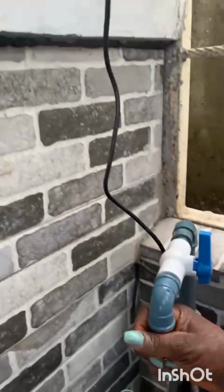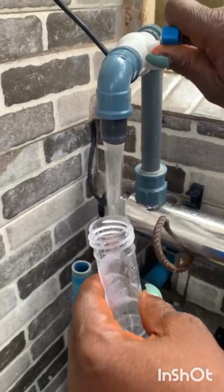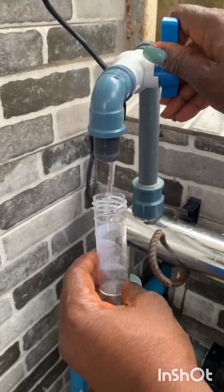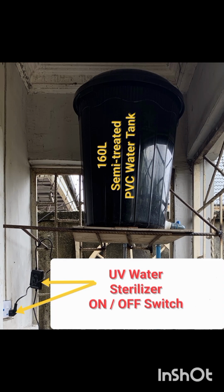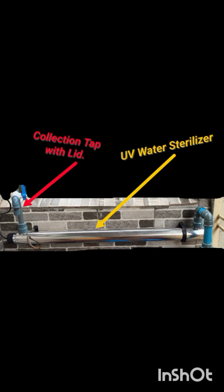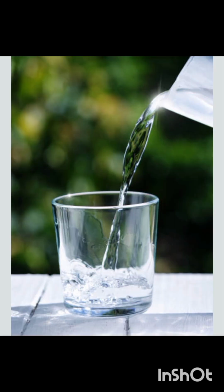Next and the final stage is the collection of safe treated water. Stay tuned. Turn on the UV switch to power on the UV sterilizer. Gently remove the protective cap and open the tap for collection of safe treated water for drinking and other domestic uses. Water flows from the semi-treated water tank through the microfilters for further filtration and finally through the UV sterilizer for disinfection and sanitation of the water, that is, killing bacteria and germs, thereby making it safe for drinking and other domestic uses.